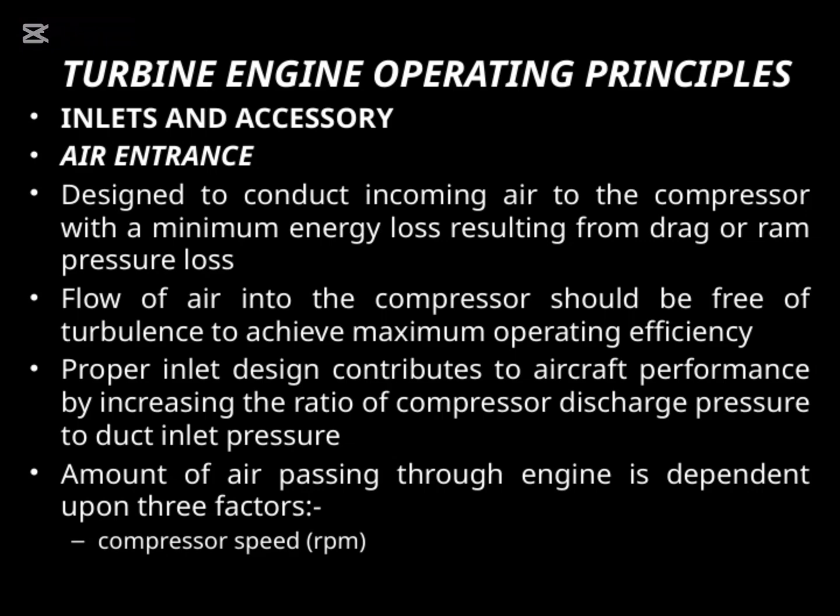So, a properly designed inlet not only helps maintain smooth airflow, but also enhances overall aircraft performance by increasing the ratio of compressor discharge pressure to duct inlet pressure. Finally, the amount of air passing through the engine depends primarily on three factors, with compressor speed, or RPM, being a key one. As the compressor spins faster, it pulls in more air, which is essential for generating the thrust needed for flight. All these elements work together to ensure the engine operates efficiently and reliably.